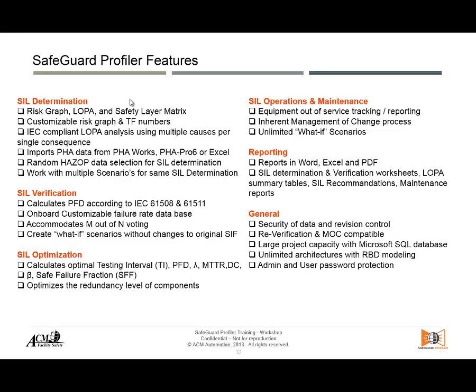So this tool allows you to keep records of that and to fine-tune them, which is very good to have in your onboard customizable failure rate database. Don't trust too much on generic ones, so use them of course, but pay attention. They belong to you now, and if you already have an installed valve, well, it's not anymore a generic valve. It is a valve that belongs to you with a specific brand and name.